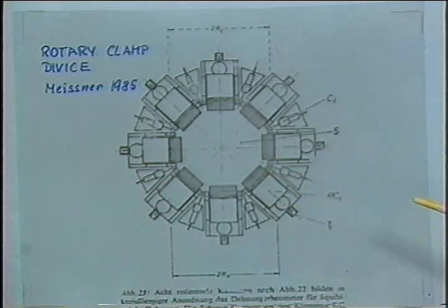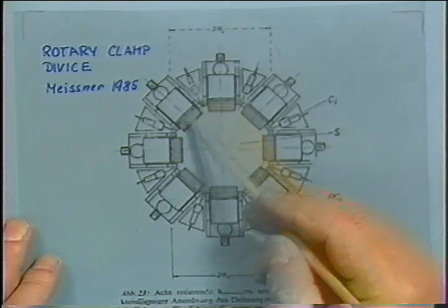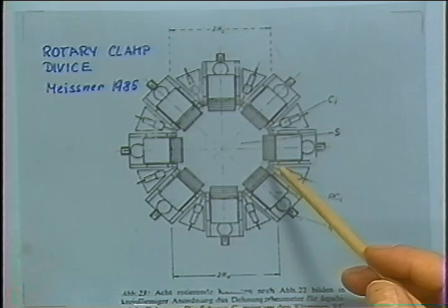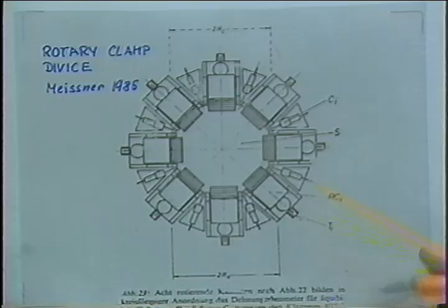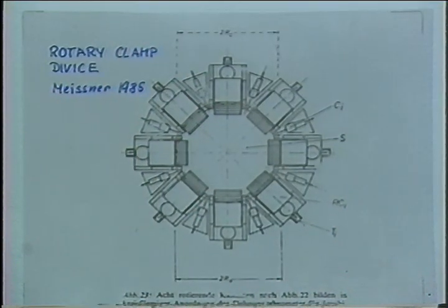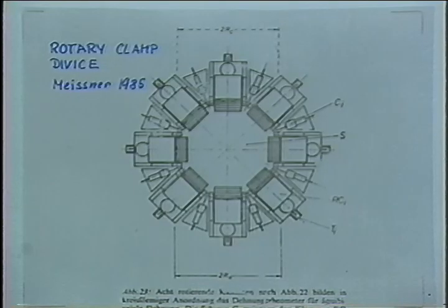So you could produce extensions everywhere between the axisymmetric case, this would actually be biaxial extension, and planar extension, where you just hold in one direction and pull in the other. So you can get data at intermediate rates.